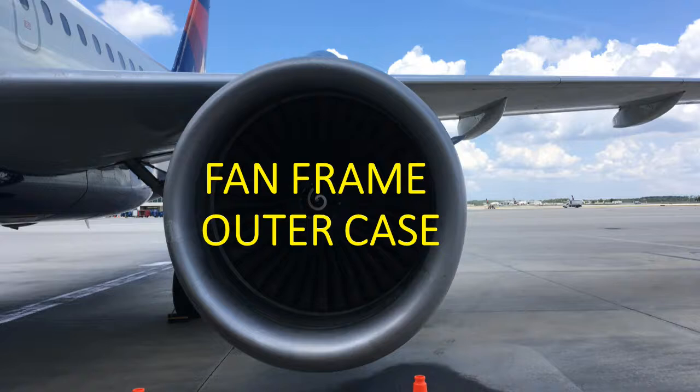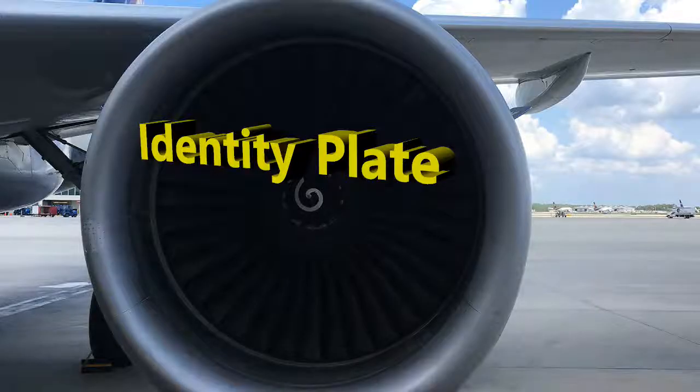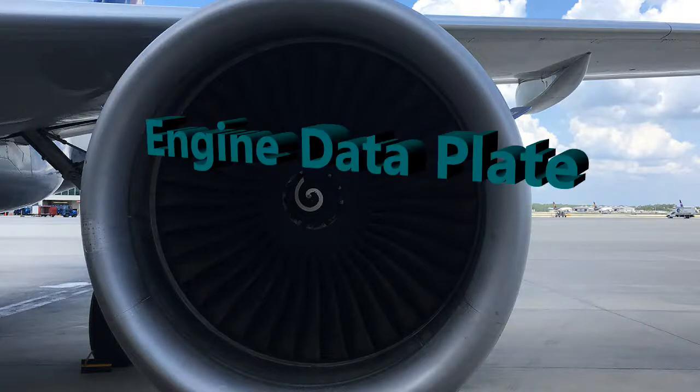You have an identity plate between 2 and 3 o'clock, the tech insertion program identity plate. And then of course the engine data plate is at the 3 o'clock position, on the surface of the outer case of the fan frame.